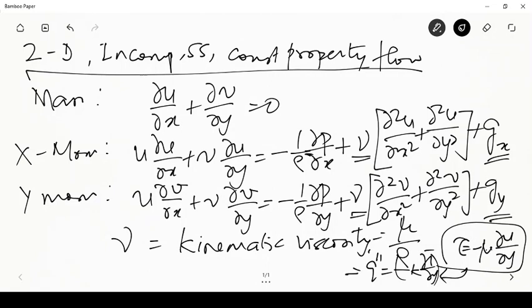So just like your heat flux is proportional to the temperature gradient and the constant of proportionality is the thermal conductivity, which is a property of the medium, when a fluid flows past a surface, the shear force that it exerts, that is the force that if I have a surface like this and a fluid is flowing like this here, it exerts a drag on this surface, which is basically a shearing force on the surface, and that force is going to be proportional to the velocity gradient in that direction. Okay, the velocity gradient at the surface multiplied by a property mu, which is a property of the fluid.